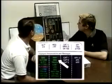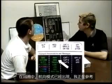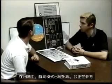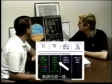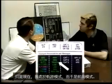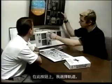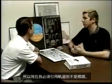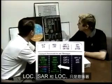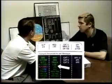What about heading? Heading just means I've pulled for a selected heading, or I've gotten myself into a version where a heading mode has come up, and I'm referencing whatever is selected heading. Track? Track's the same thing, except now I'm in the track mode instead of the heading mode. It means that I've selected, instead of track flight path angle on this button, I've selected track, so now I have to reference a track as opposed to a heading. LOC* and LOC just means that the localizer portion of the ILS system has been engaged.